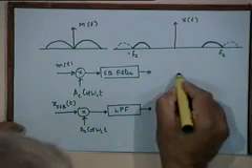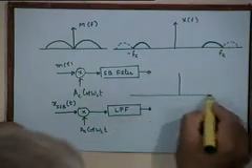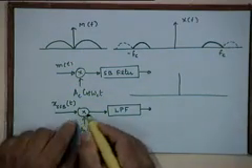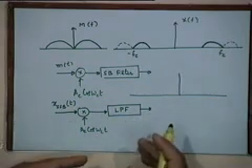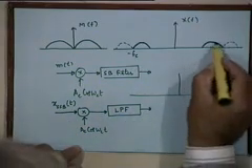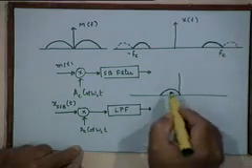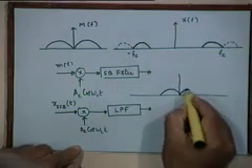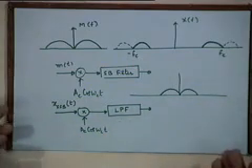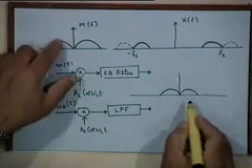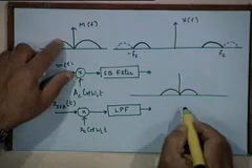In the frequency domain, what we are saying is that as a result of this multiplication, the same frequency translation is happening again. This part of the spectrum will come here, and this part of the spectrum will go here, and because of the symmetry, it will be precisely the same M(f) that we started with.